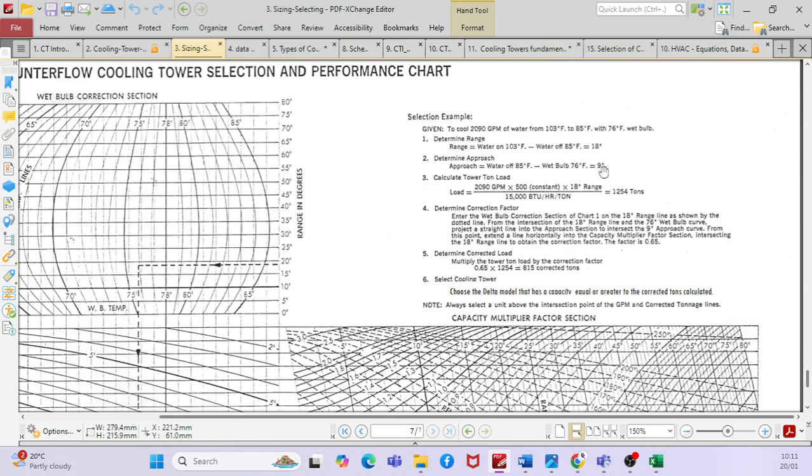No, I understand. But what I'm trying to say is, for chilled water temperatures, it is not 8 degrees C, it is 8 degree K, right? See, what I'm saying, that is a delta T, right? The delta T that you're trying to say, you can say in C, or you can say in K. Both are the same value, right? I just want to confirm that. Yeah, both are the same.